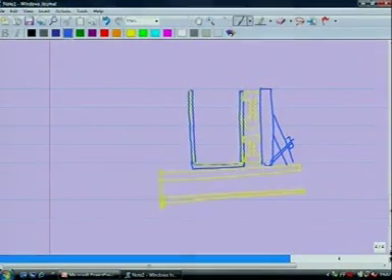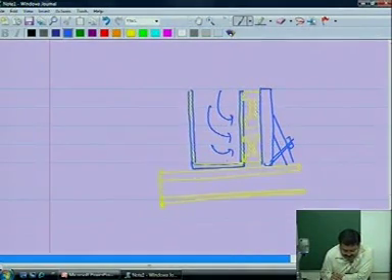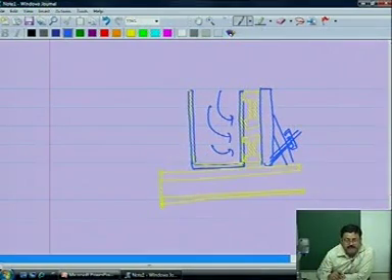So can you visualize how the pressure is taken care of? For this height, concrete pressure is exerted on this, and this gets balanced by this clamping arrangement. So you have this nut through which you can tighten it, and this member has a clamping arrangement here.